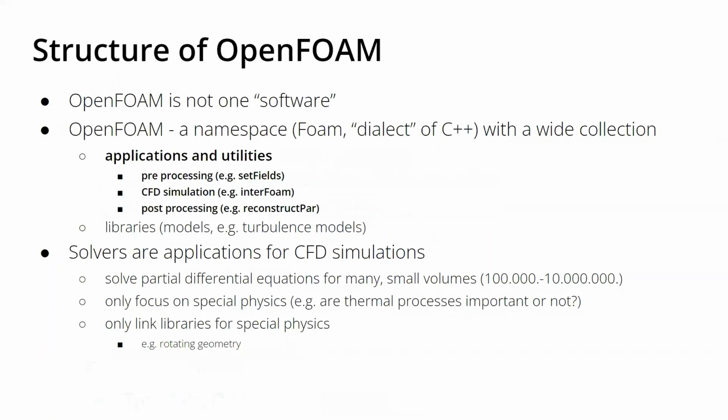So a short introduction to OpenFOAM, if you don't know what OpenFOAM is. Now, OpenFOAM is not one software like you would consider AutoCAD to be a software where you click something and then a GUI comes up, or Microsoft Word, or just Notepad++. OpenFOAM, if you take it seriously, is actually foam, which is a namespace, a dialect of C++, with a wide collection of two things.